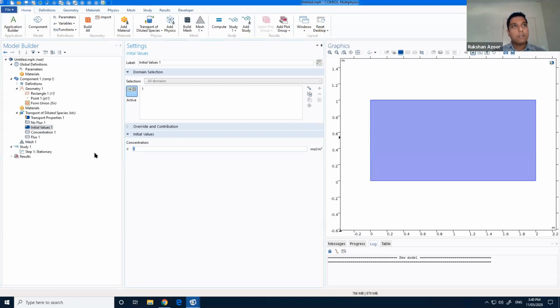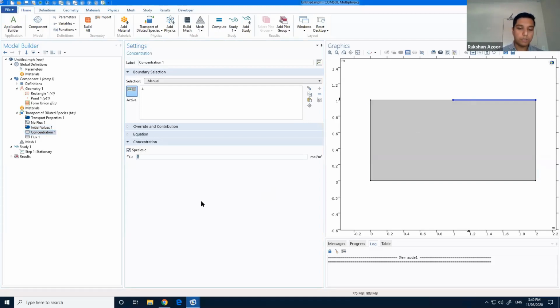But if you have a value that is close to the solution, it makes the solution easy. So let's just give 8.6, or we can give cref just to be consistent. So concentration, we had to define it to be cref on the top surface, half of the top surface. And flux would be, again, species C. It has to be negative.